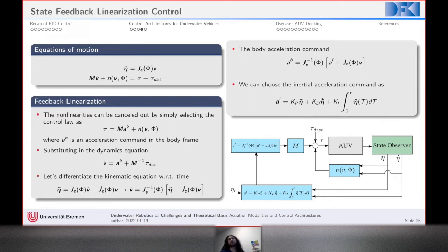Not a 3D point cloud, but an occupancy grid, like an octomap or octree representation. Then we give that to a path planner that uses RRT with a certain time to find a solution, and the propagation function in the RRT or RRT star is the kinematic equations of motion. So at least we guarantee that the path that this RRT is giving us can be traced by the vehicle.